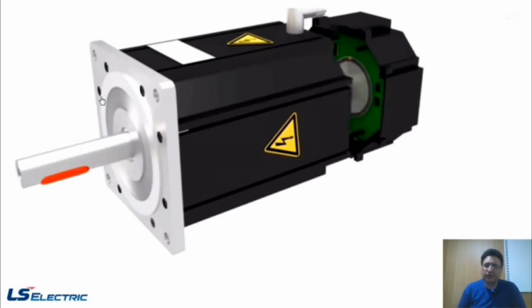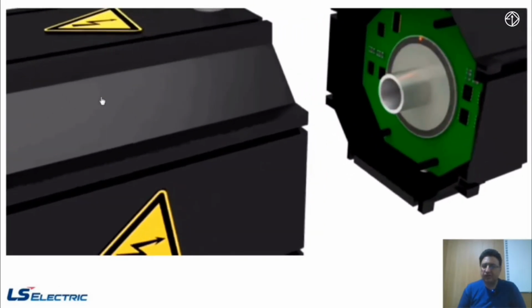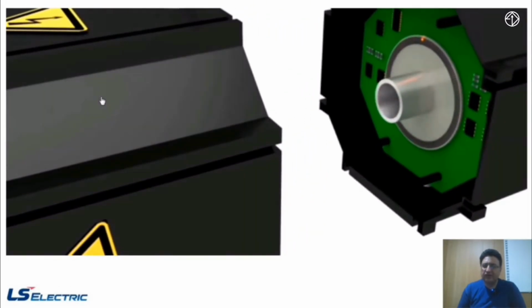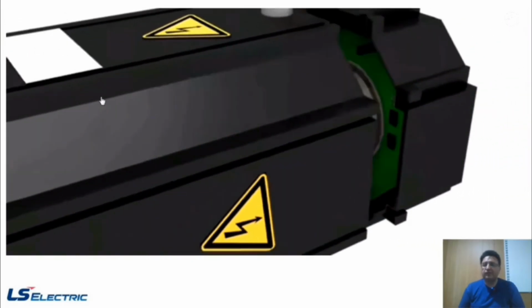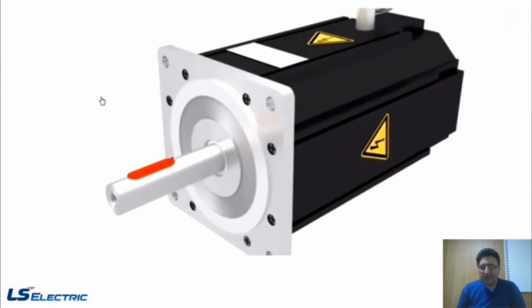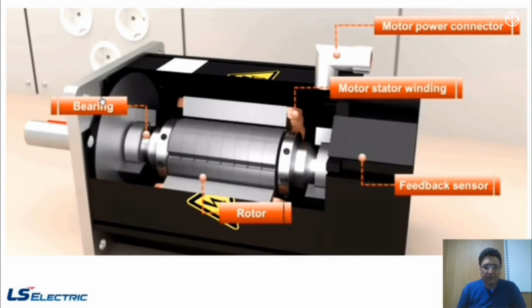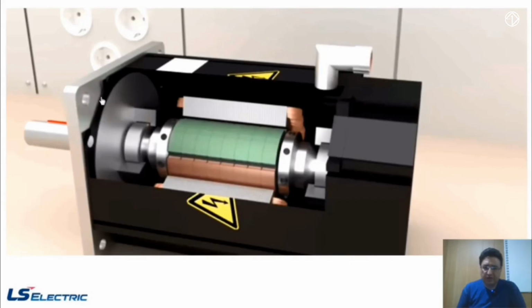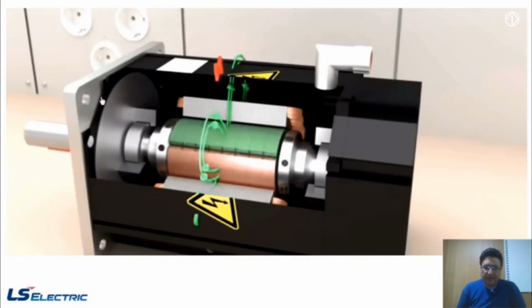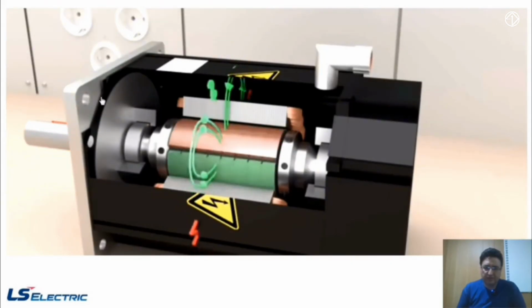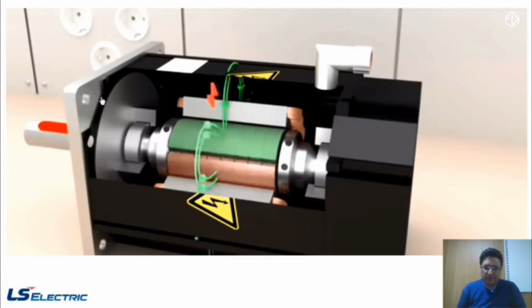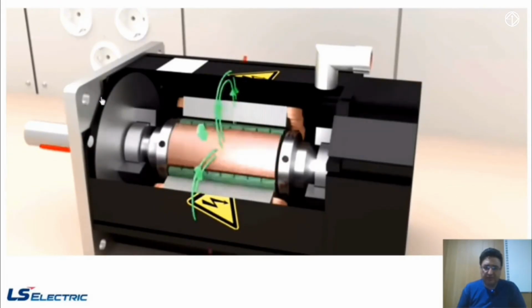At the end part of the motor, an encoder is used, which we can use as feedback, and it can inform the drive about the position of the shaft and the motor. And in this image as well, you can see the internal components of the motor. And as you can see, this servo motor can provide us with extremely precise movements.